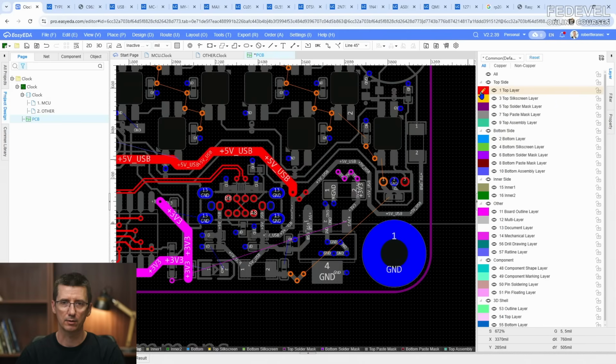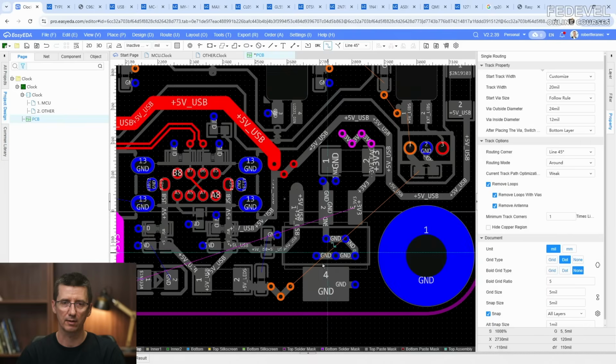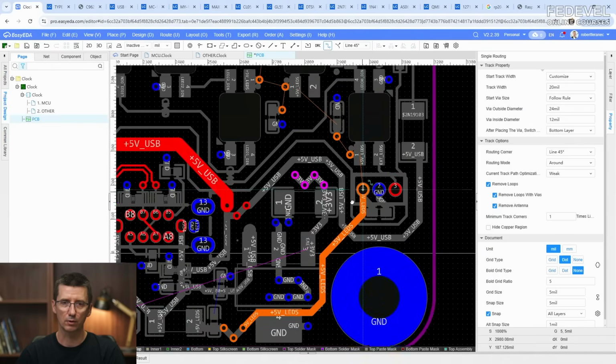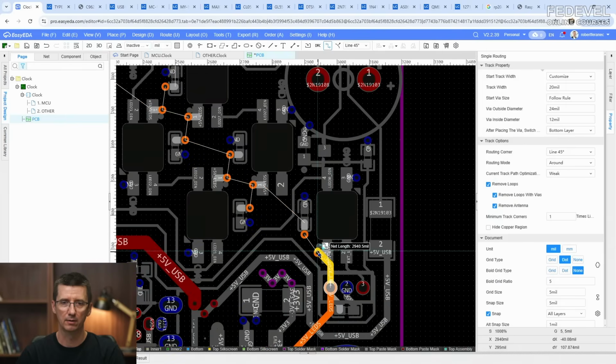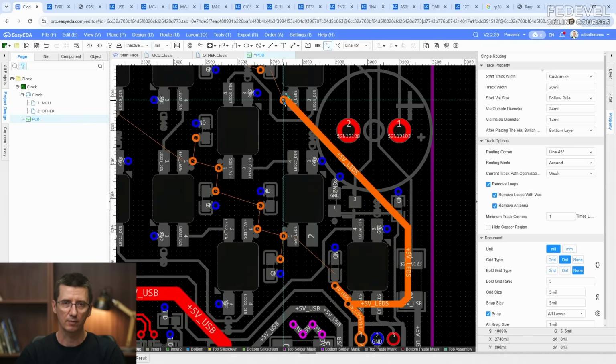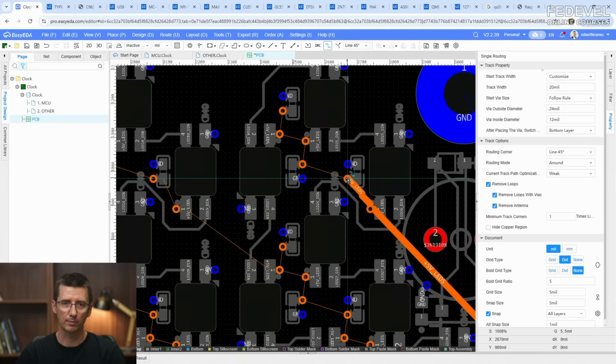Right now we will just try to connect everything. This is how I usually do layout. In the first stage of layout, I just focus on connecting everything. And once you connect everything, then you can do some kind of optimization, because then you will see where you have some space. And by the end of the layout, I draw the polygons, because sometimes it's very hard to see through polygons and planes. So that's why I do it at the end.